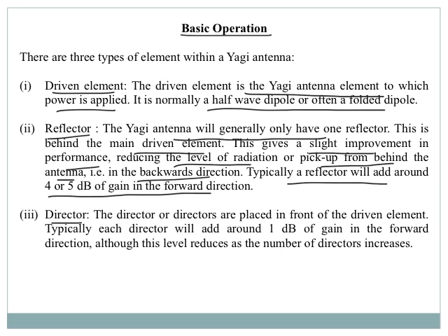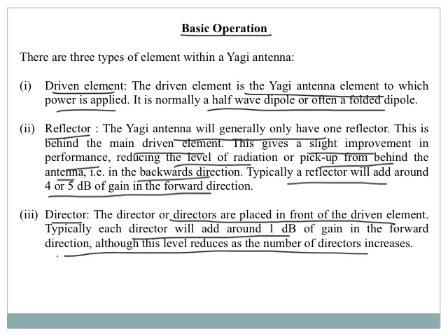Now coming to the director, the directors will be placed in front of the driven element, and typically each director will add around 1 dB of gain in the forward direction, although this level reduces as the number of directors increases.